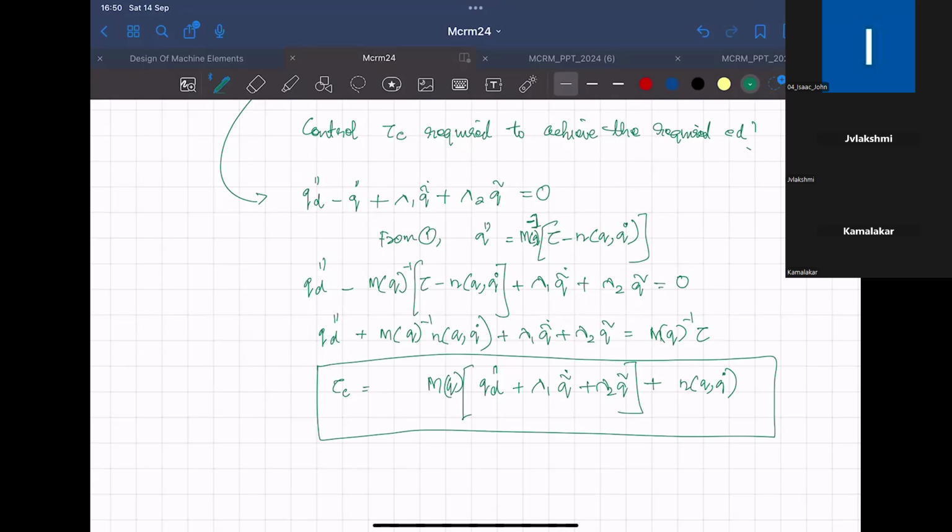And here the answer is the tracking error tends to 0. That is the theoretical one, sir. If you had given the option tends to infinity or tends to 0, then we might not be getting the doubt here. But when the option is that the tracking error is bounded, that means definitely there will be error, because we are not touching that particular x-axis, sir. When we draw the curve asymptotically, we are drawing it parallel to the x-axis. Is it true, sir?